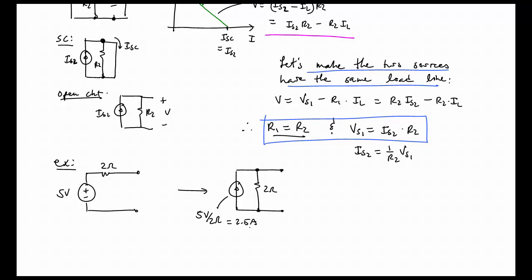Now what's the power of this? The power of it is that at these terminals, if I draw a box around this source and this source here, if we put those in a black box, if you simply look at the current that's coming out, or that you're drawing out, and the voltage across those two terminals, you would not be able to distinguish whether you had the first circuit or the second circuit.